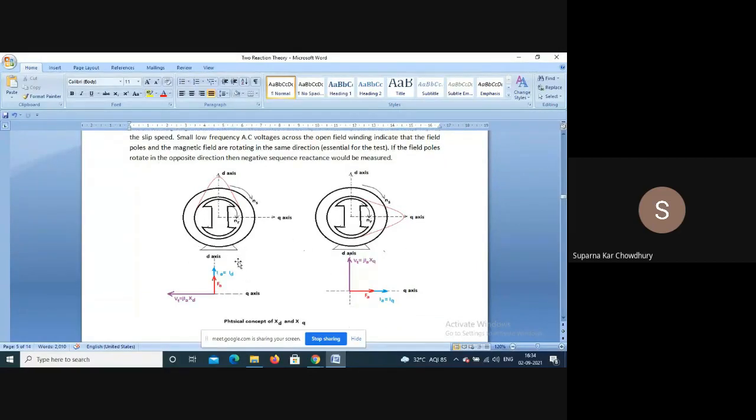Now about the voltage, what we have applied is a small voltage, around 25% of the rated value. So there will be a drop in the leads and connecting wires.